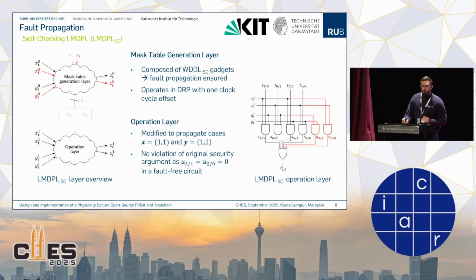Similarly, we adapted the LMDPL scheme to the self-checking LMDPL, where we used self-checking WDDL gadgets in the mask table generation layer to also ensure the fault propagation in that layer, such that the DRP protocol is now also executed with 1 clock cycle offset in the layer to the operation layer.